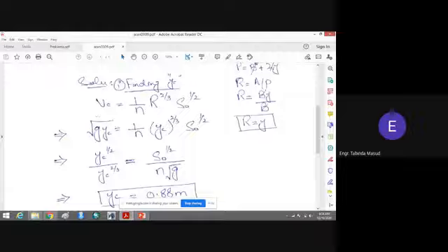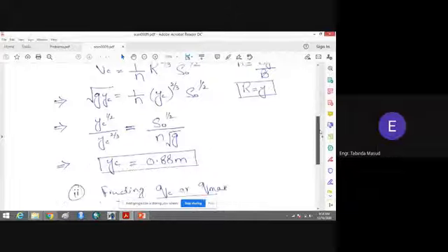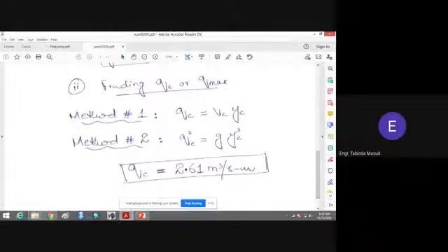Just put the values. Now there is no need to use this term g yc. n is known to you, hydraulic radius is equal to yc is now known to you, slope of the channel bed is given to you, so you can find the value of the velocity, and you can use this to find the critical or the maximum discharge. This is the second method.